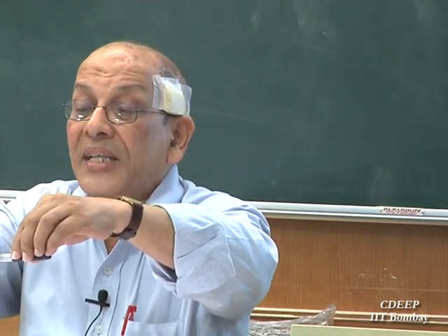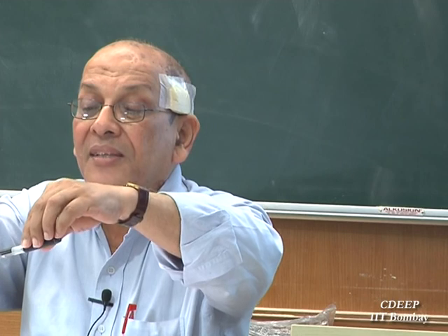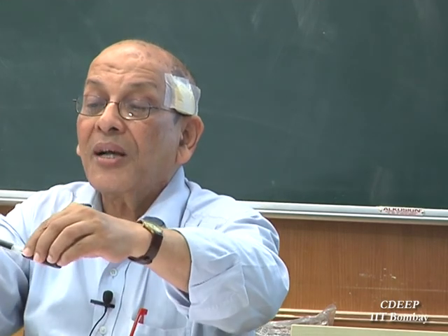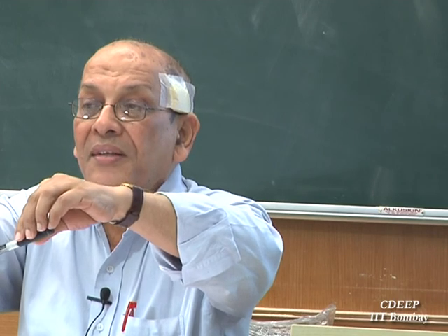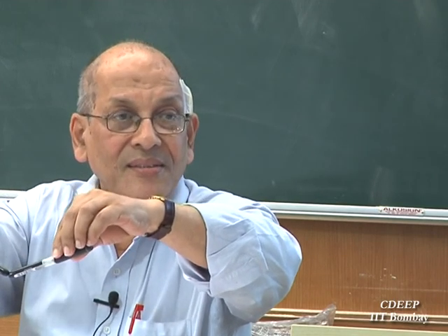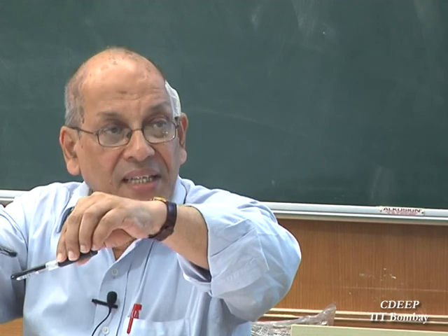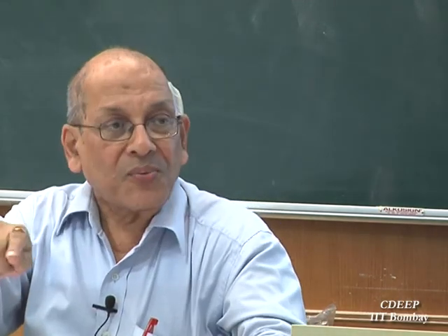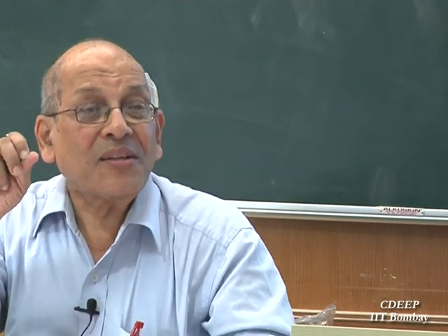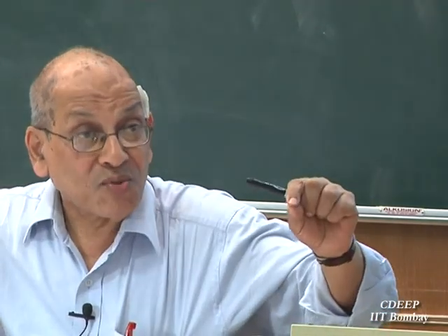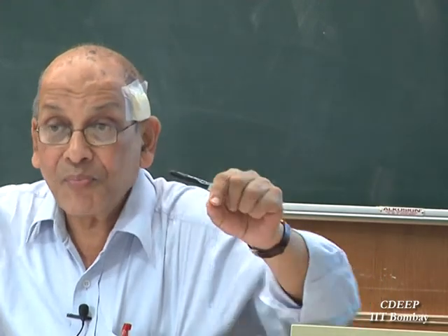Now once the entire section becomes plastic, it will become like this, from here like this, a triangle. And we say that at that level, a plastic hinge forms at the center. It is not a physical hinge. At the two ends you have got a physical hinge, a pin.